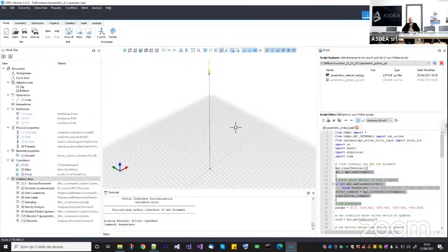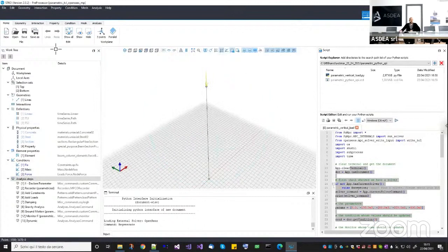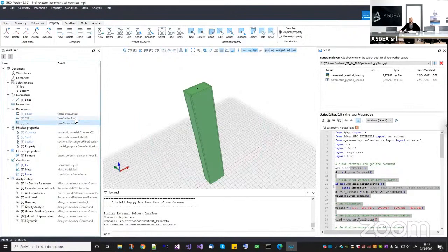You can either use OpenSees MP, doing some TCL scripting, or you can use the Python API inside STKO to directly parameterize the model. This one is a little bit more complicated, but it will be more powerful. So I will start instead with how to parameterize a model using TCL. This is the same model you have seen before with the 2 time series.